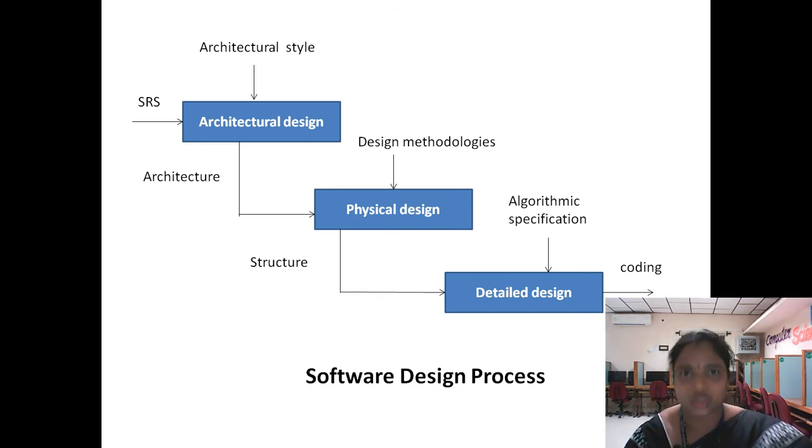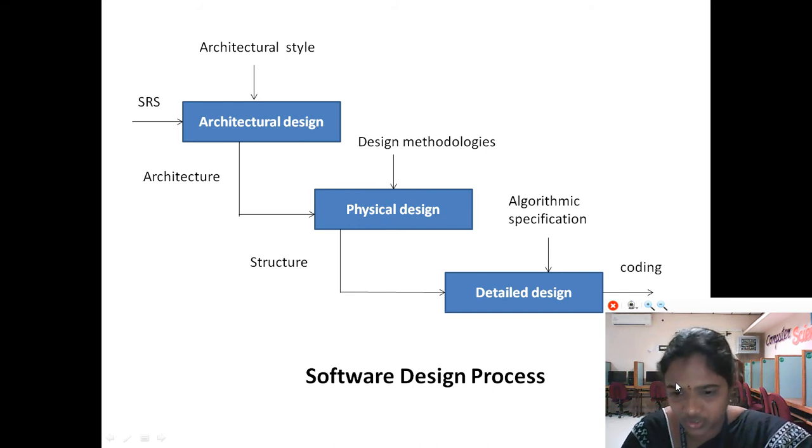So coming to the construction of the house, what is done under the detailed design? The builders prepare a detailed design in which construction drawings and written specifications are put together before starting the construction work. This may include dimensions of the floor plans, selections, engineering plans, electrical, mechanical, structural and civil engineering plans, landscape plans, final interior design plans, energy report, specifications of materials, methods of construction.